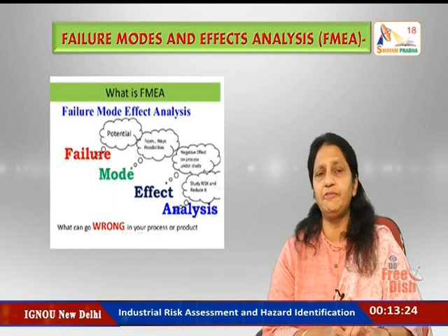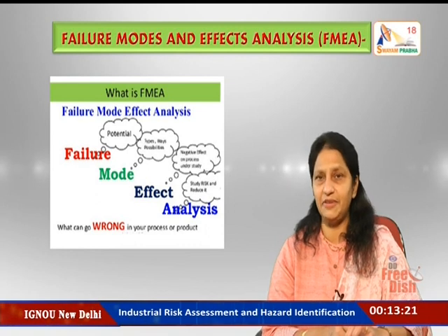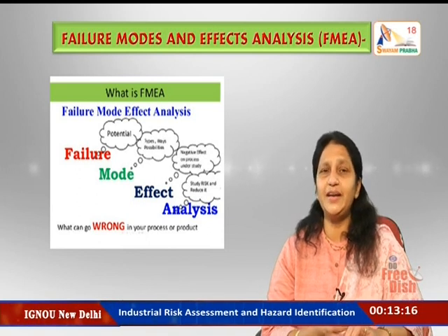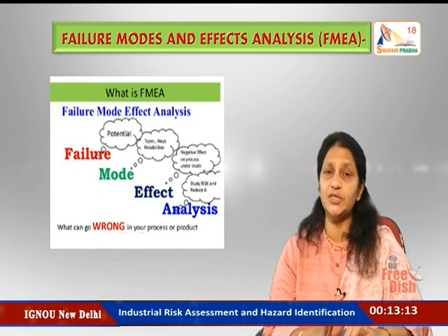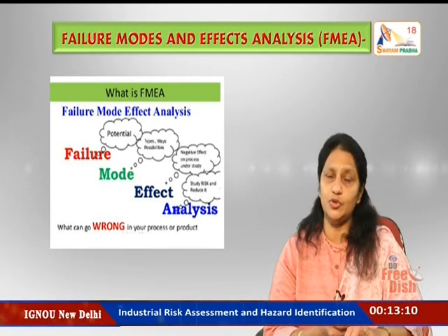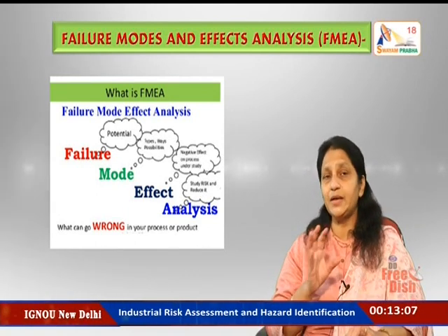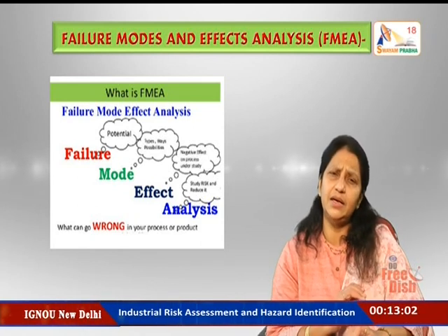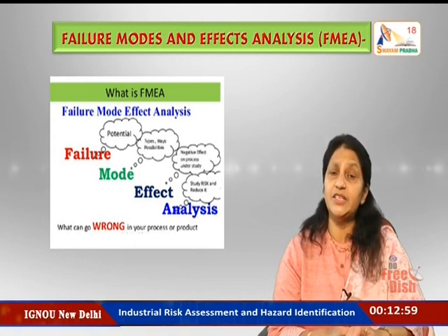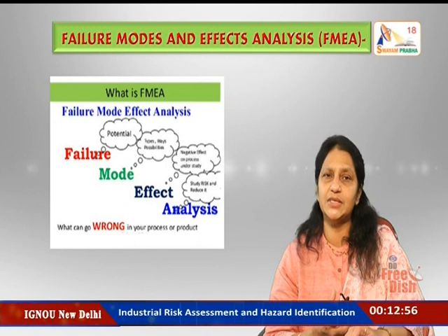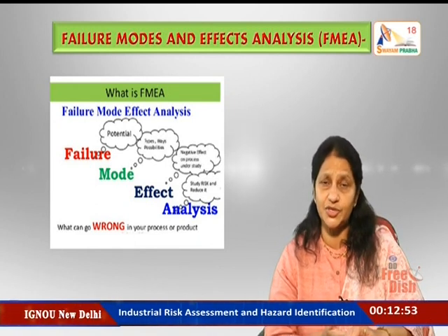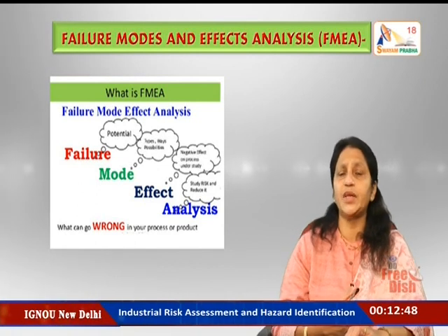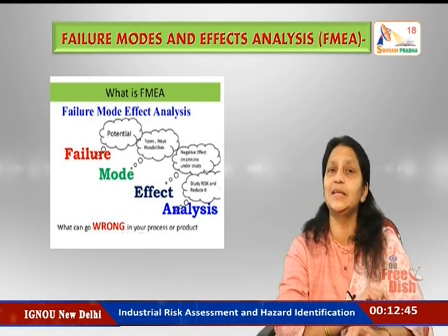And the next is the FMEA, that is the failure modes and effects analysis. The main purpose of this method is to identify potential hazards associated with a process by investigating the failure modes, that means previous experiences of why the method has failed, for each of the process items. It has difficulty in identifying hazards which require the failure of more than one process item, because of the complex interaction of the failures. Some possible steps can be performed during this analysis.